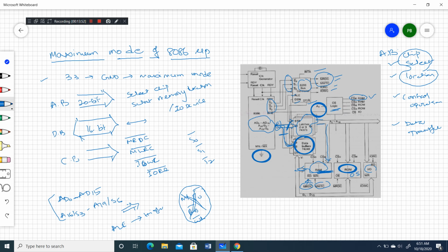That is the data buffer. The data buffer is going to get the other two control signals, that is data transmit or receive, and data enable, right? If data enable is 1, that is data is available on the data bus. Data transmit/receive bar is 0, right? It is receiving the data. If it is the read control signal, this is going to be 0; for the write control signal, this is going to be 1, right? So like that, the data transfers will take place.